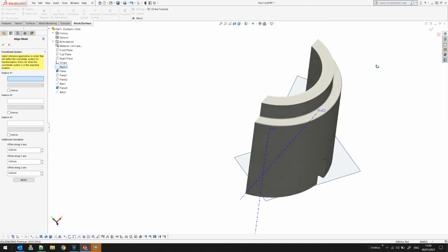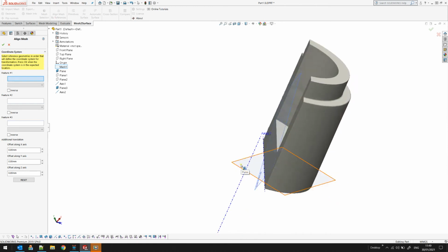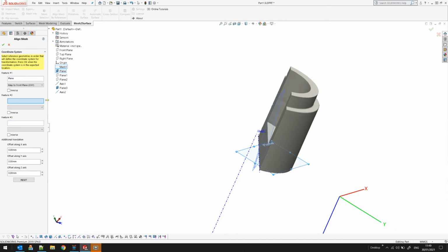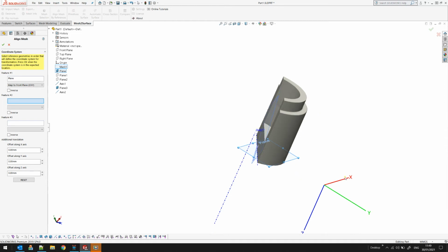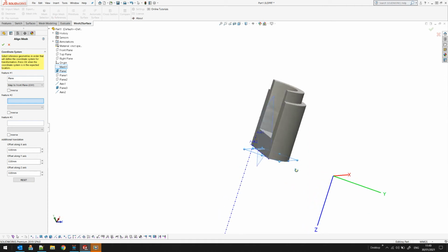So let's think now, what do we want to achieve? What I want now is I want to take this plane and tell the software which plane this is, and in this example it automatically will suggest that this is my front plane, which is an OXY plane, as you can see on the screen. Now it's interesting that we provided a constraint to this algorithm on how to define the coordinate system, and as you can see, this is what it does.